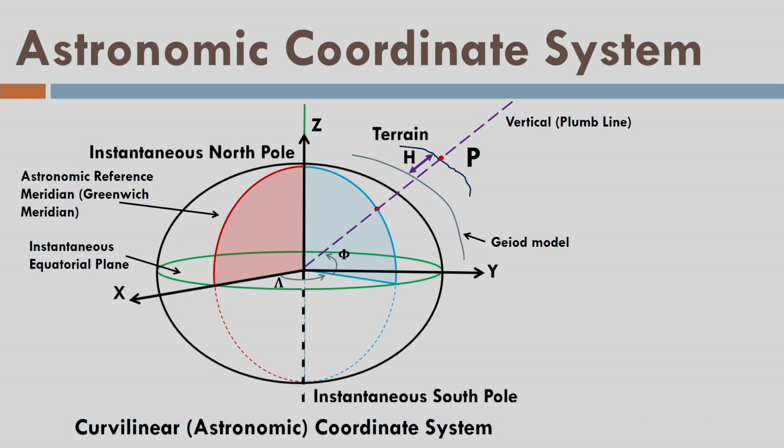Orthometric heights are defined with respect to the geoid. Okay, what about the role of the ellipsoid here? So far we did not find any role of the ellipsoid, although we are showing it here for the purpose, and the purpose is that the height between the geoid model and the ellipsoid is called geoidal undulation and represented by Ng.